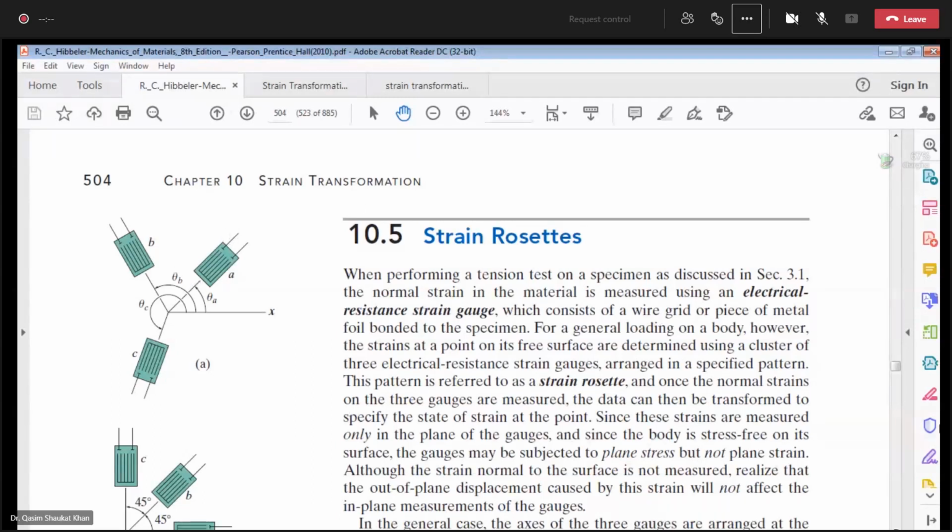When you get the strain gauge, particularly the Chinese strain gauges, they have very short leads. So you have to attach wires so that we can connect them to the data acquisition system. As the load is applied, stress, which is force per unit area, changes, since the cross-sectional area is fixed. With changing stresses, strains will be produced. The strain gauges will measure the strain and it will be recorded in the computer system. We have that assembly in our lab.